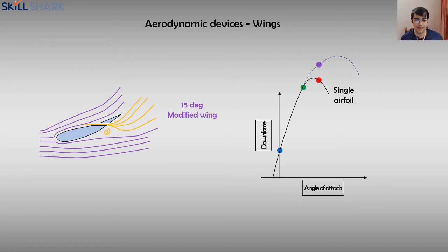And you can see in this graph, for that same angle of attack, we didn't do anything to this yet. All we did was create a slot. So for the same angle of attack, you have more downforce, and the effective graph also changes, that potential graph. Smoothen out those edges. Instead of having this little rough cut, let's join the trailing edge over here and smoothen this edge, and there you go, you have two elements.